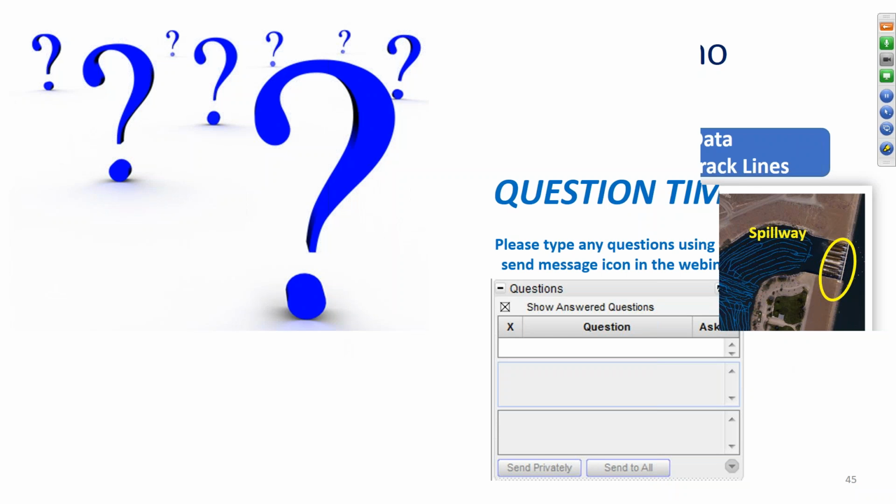Okay, so to that point, what we do is process the bathymetric data that you provide us, and in terms of classifying as a true hydrographic survey, we process the data based on what is provided to us. In many cases, it's data collected with an ADCP or multiple ADCPs using a 4 or 5-beam solution. In some cases, it's using single beam or multi-beam sonars or echo sounders.